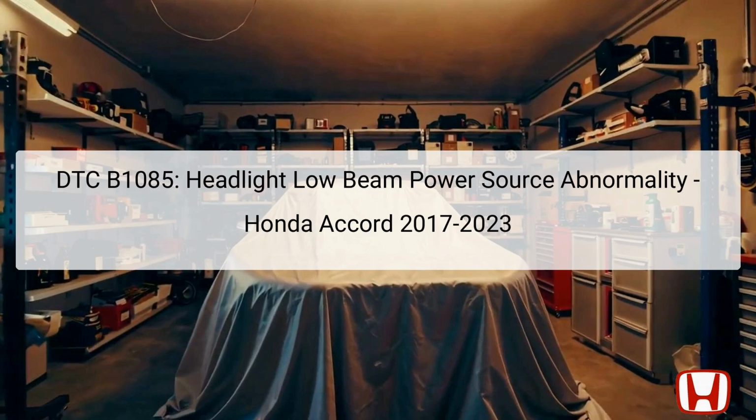The relay control module is located near the fuse box, and its role is crucial for managing the electrical signals to ensure that the headlights function correctly. If the module fails or there is an issue with the wiring, it can lead to inadequate power delivery to the headlights, resulting in the B1085 code. This code can potentially affect safety while driving at night, making it imperative to address promptly. The troubleshooting steps outlined here will guide a technician through identifying and resolving the issue efficiently.